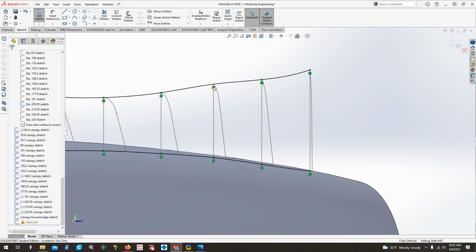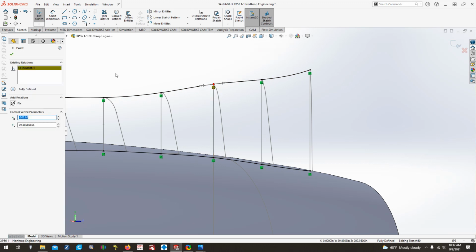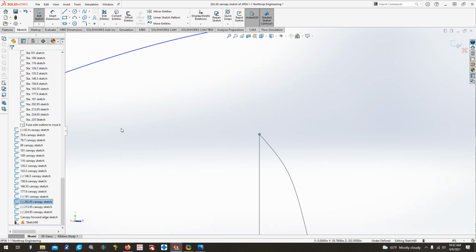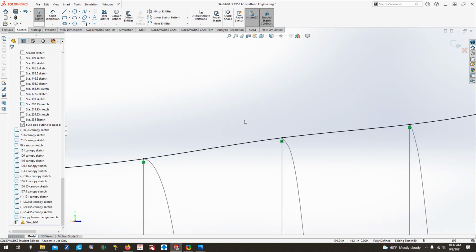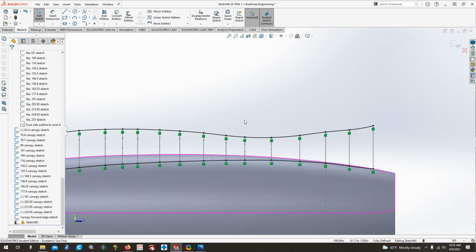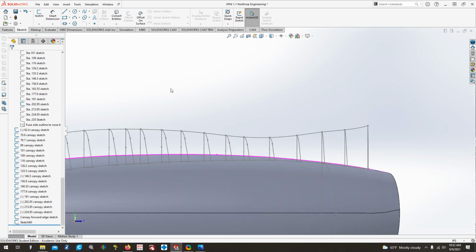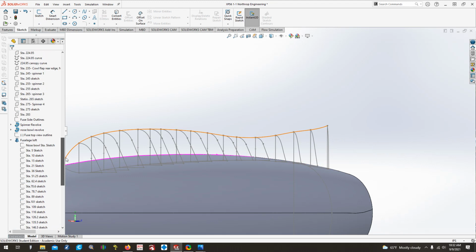And it's because of this here. The relation that we had is now gone. So we just click this point, delete that relation, move it out of the way, hold the control, zoom into the new point while you hold the control button down and say, hey, coincide it there. Zoom out. That's a little bit better, but it's still a little high. I think we're going to have to come down probably another 1/4 of an inch on that one. And this is where you get into the back and forth, back and forth, back and forth a good bit.